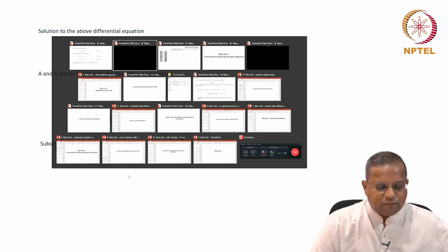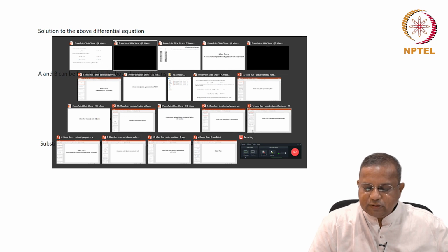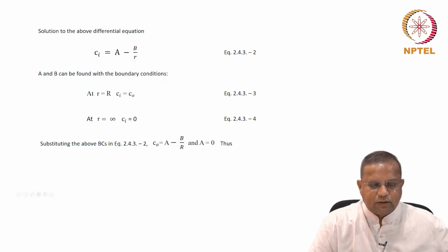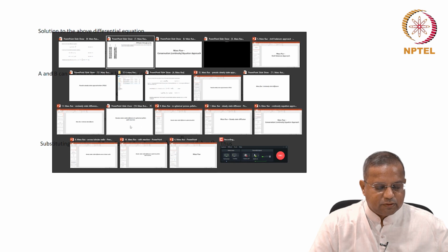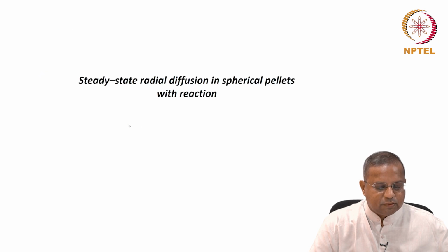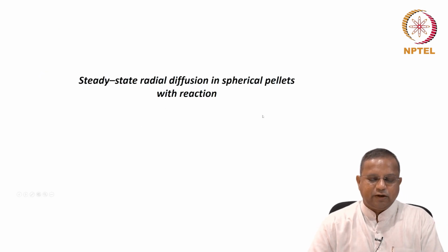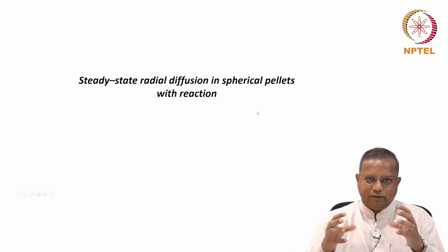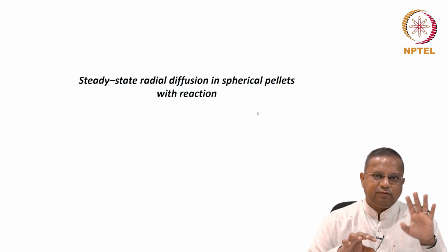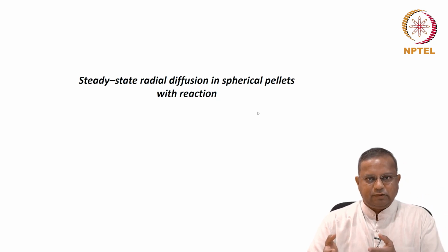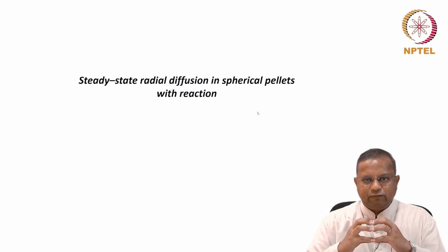Then after that we looked at steady state with a reaction term. We took a spherical pellet and then we looked at inside the pellet. The only difference between the previous times is that the previous times there was no reaction term, and here there is a reaction term. We had looked at the case of an immobilized enzyme and the reaction occurring there and